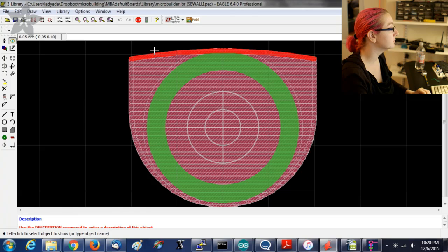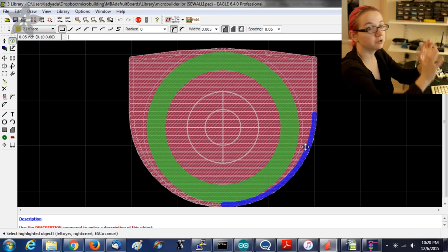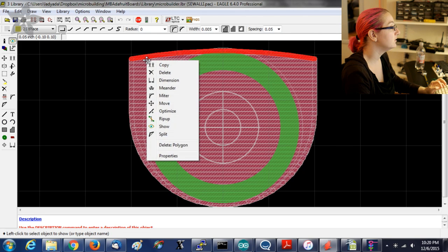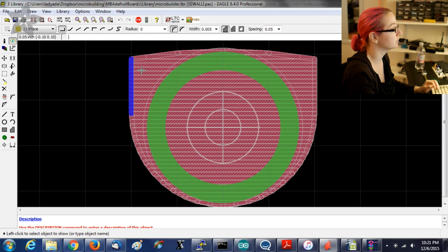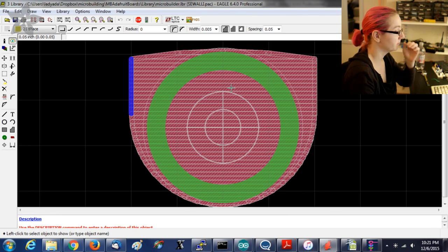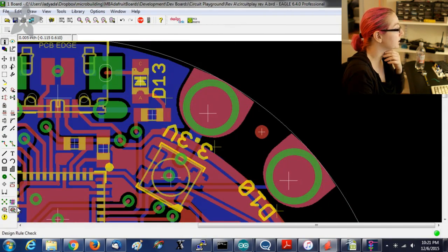this using the polygonal tool. You draw the top and bottom layer to create this sort of oval shape. And then you also need to add a stop layer as well, because it's not a true pad, right? This isn't a true pad shape, it's faked. It's actually a round through hole, and then you put a copper around it to make this sort of nice oval shape. And as far as errors, you get errors, but then you just kind of deal with it.